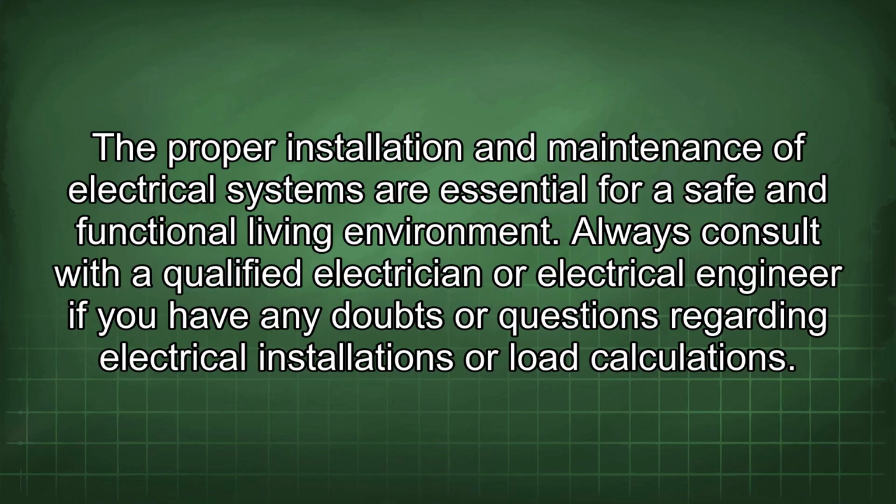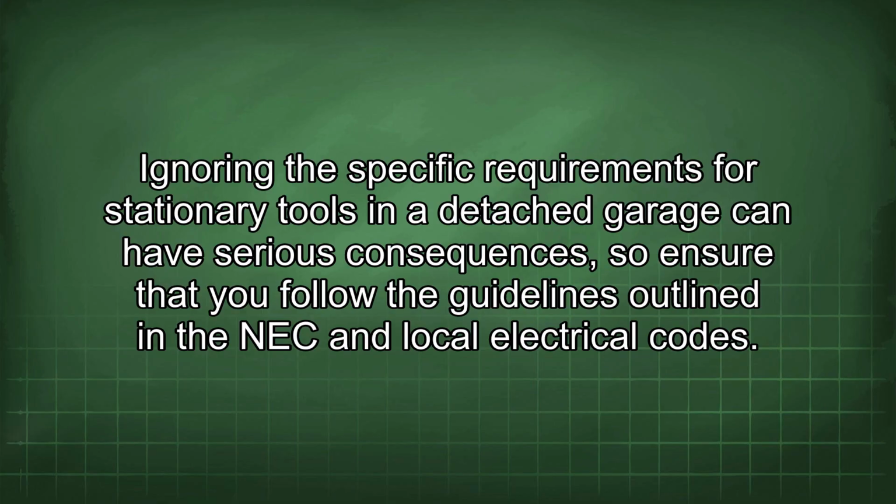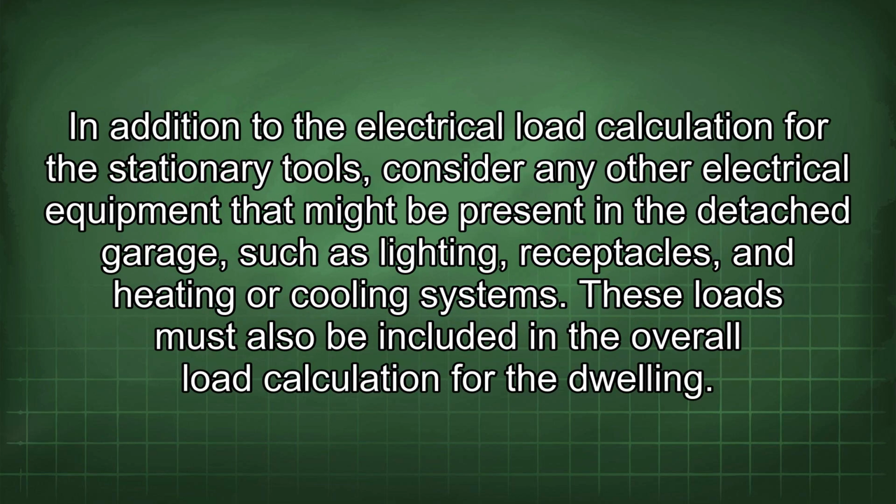Always consult with a qualified electrician or electrical engineer if you have any doubts or questions regarding electrical installations or load calculations. Ignoring the specific requirements for stationary tools in a detached garage can have serious consequences, so ensure that you follow the guidelines outlined in the NEC and local electrical codes. In addition to the electrical load calculation for the stationary tools, consider any other electrical equipment that might be present in the detached garage, such as lighting, receptacles, and heating or cooling systems. These loads must also be included in the overall load calculation for the dwelling.